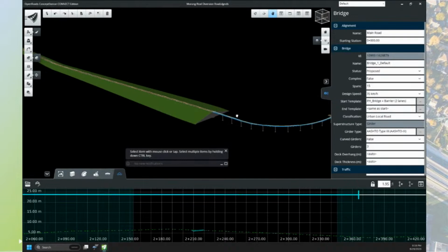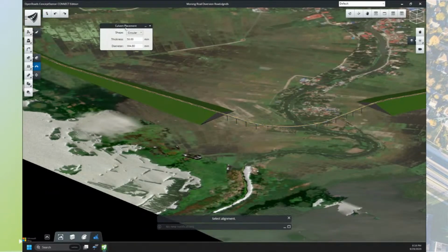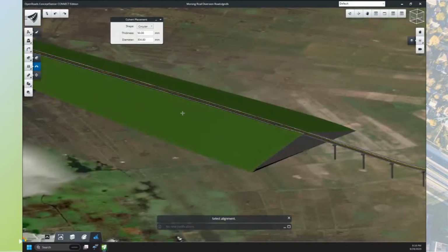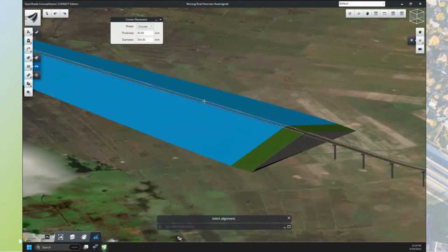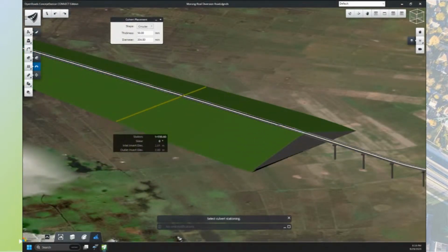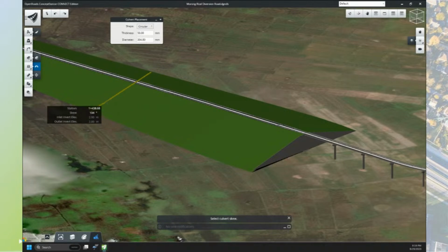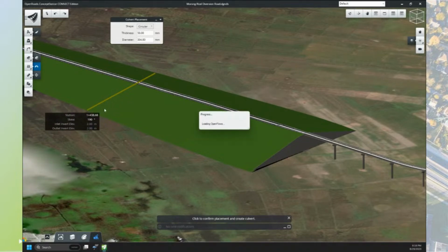Okay, there. So if let's say we're okay with this and then you want to add maybe some culverts, there's a tool that will allow us to add some culverts, lalo na in this area where we're in its slope, right? So I'm gonna select the alignment and then notice as I move my mouse, it's actually creating a preview of how the culvert will be placed. So I will click somewhere here just to demo it for you guys, right? And then I'll just left click to accept.